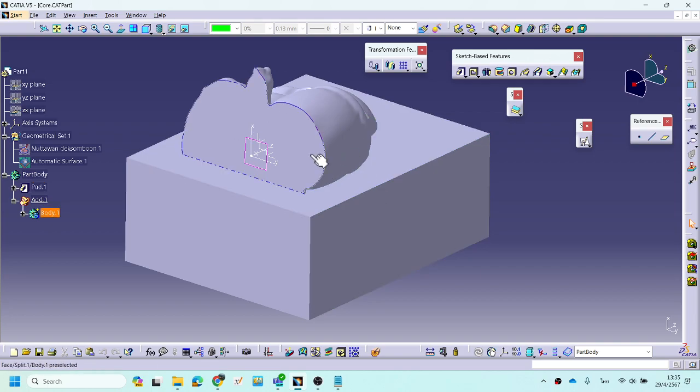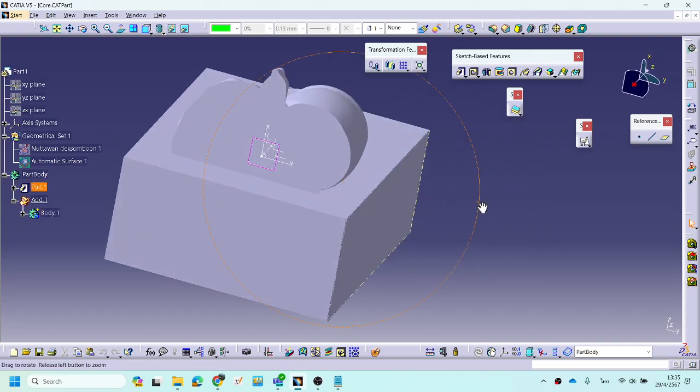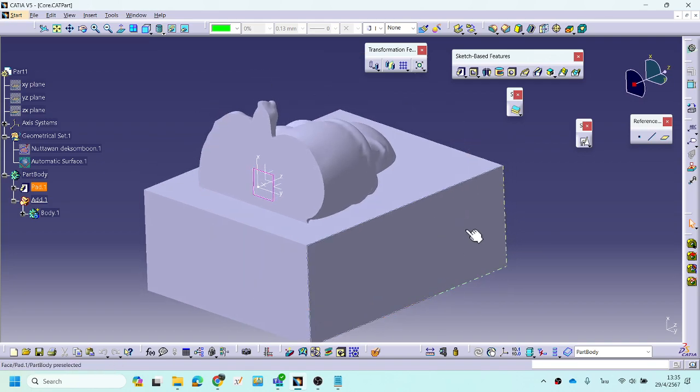I define the new origin, and the orientation is the new orientation. The workpiece z-axis points to the right, and in the surface machining in the CAM module, I sweep the z-axis to point up. You need to point the z-axis up in the surface machining module, right?